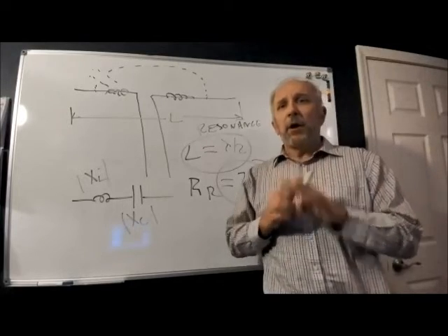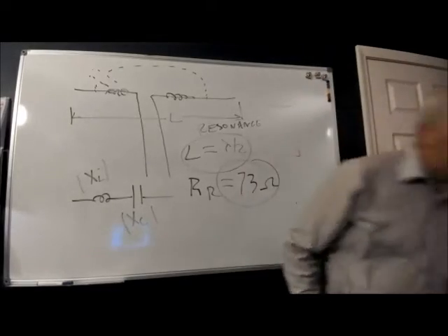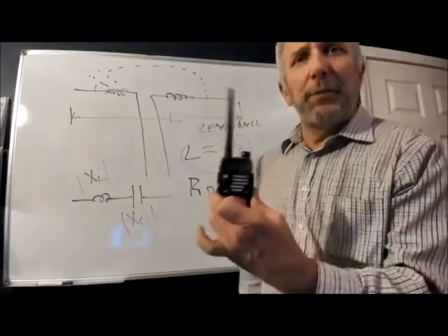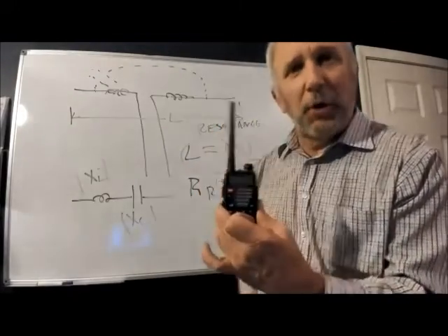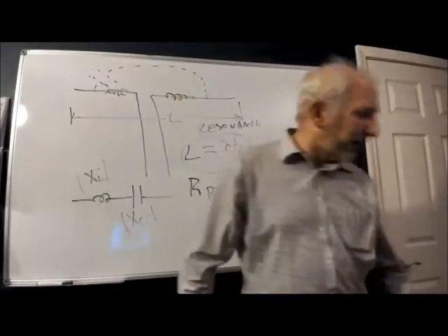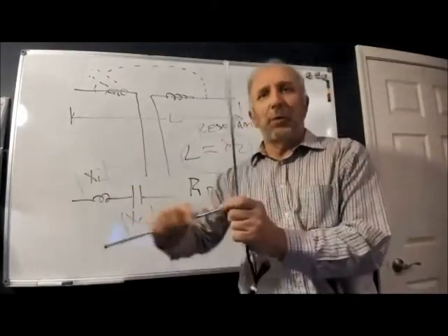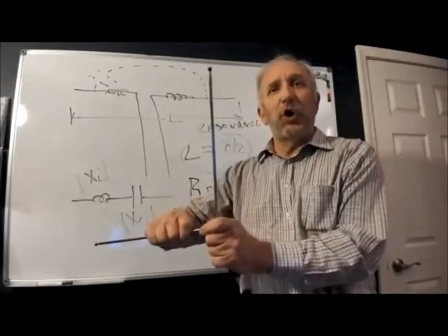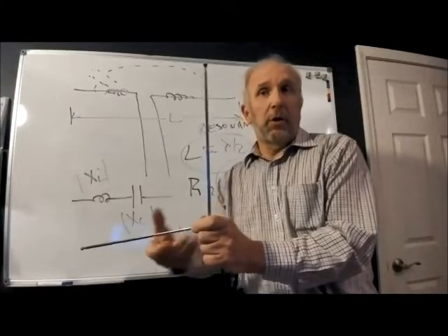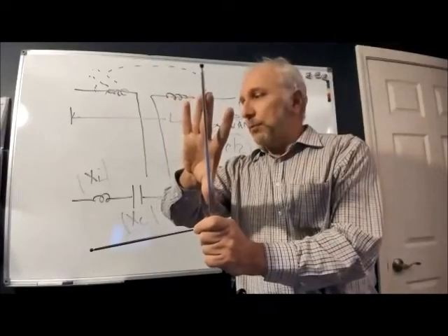Okay. There are times when dipole antennas are kind of unhandy. Something like this, if, again, John talked about walkie-talkies, a dipole antenna on this might end up poking out people's eyes. So we do something interesting. We take the dipole antenna and we just basically cut off one half of it, or we make the return path, maybe, the structure of a car or a vehicle, or someone's holding that. It means we end up with one half of a dipole antenna.